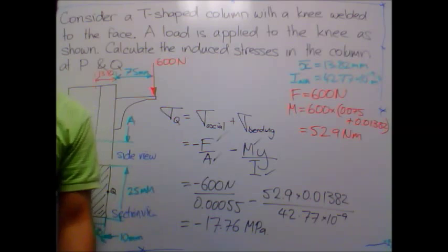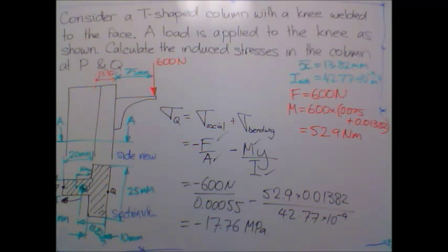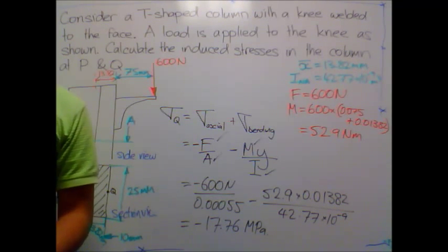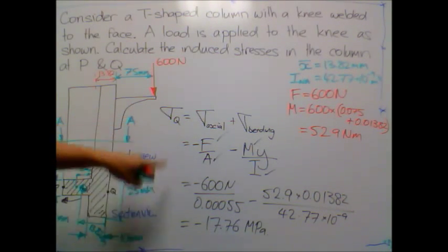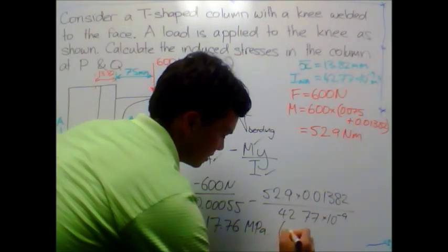Awesome. Okay, this is the end of this question. So our final solution is stress at P equal to 19.32 megapascals, and that's in tension. And my stress at Q is negative 17.76. This indicates that it's in compression.